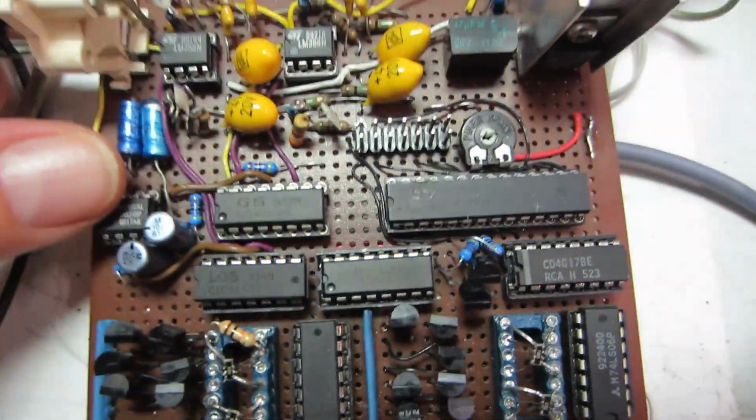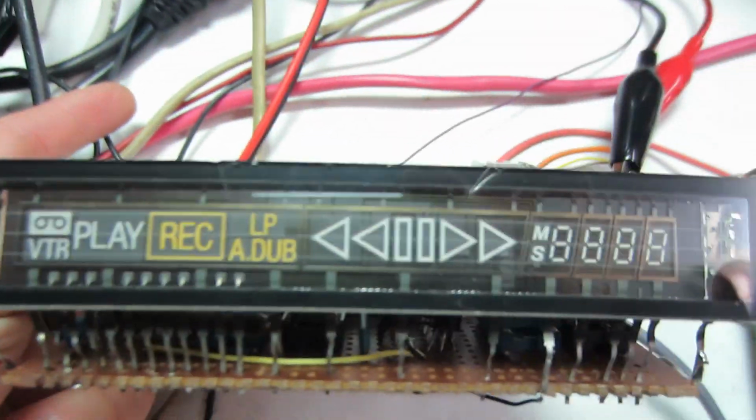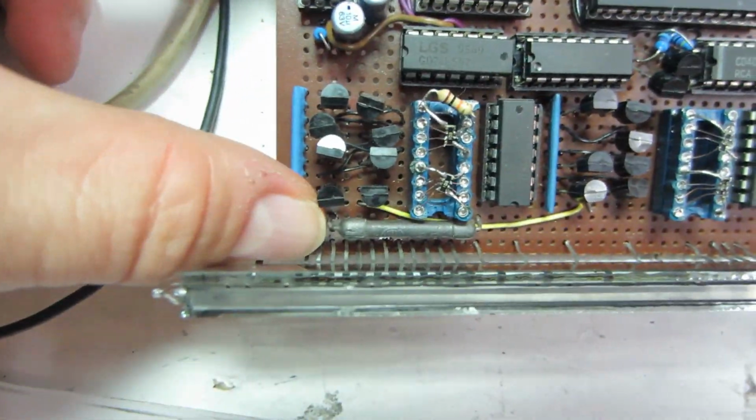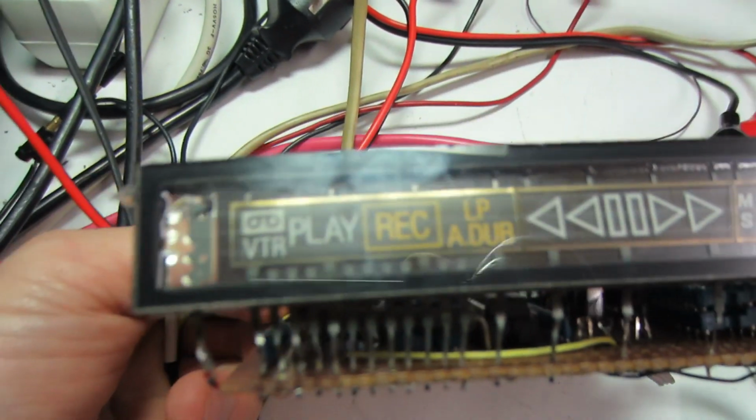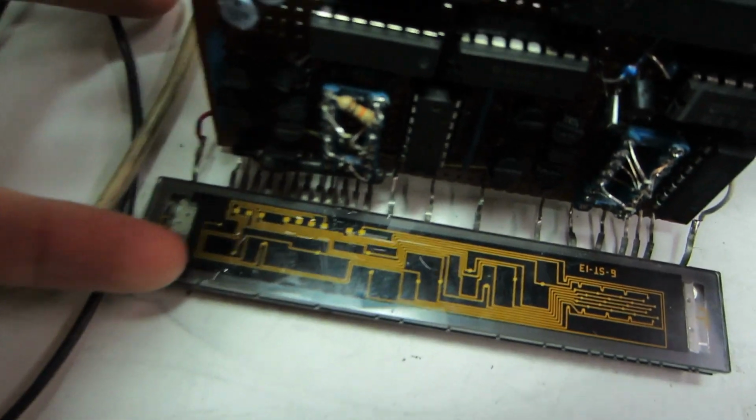Okay, I forgot a few tidbits. One thing is that you should run the filaments on AC. I cheated. I run them off 5 volts through a 16 ohm dropper resistor. And if you want to know which of these pins goes where, well, you can easily see it. You can see which pins go to the meshes, and if you wanted to know which pins go to which segments, then you can see that on the back side.